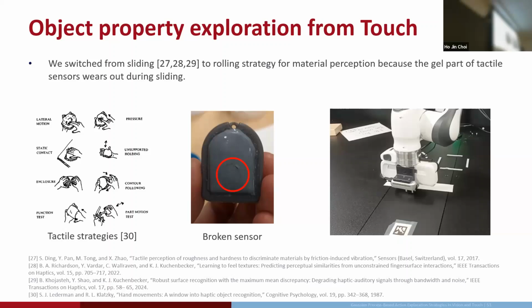I think for vision only, a NeRF kind of method offers a good way to measure actual information gain. Gaussian splatting also gives an explicit representation of the environment and has a very efficient calculation of the hashing to calculate the information gained. On the vision side, I feel like Gaussian splatting is a good way to do it. But incorporating tactile data seems to be not intuitive, because you have to combine your uncertainty location to the surface while finding a maximum information gain. And I felt like the distance function that the GP gives us has a better capability of doing both at the same time without going back and forth.